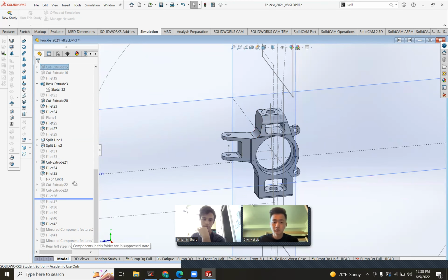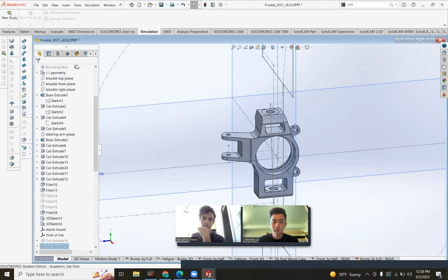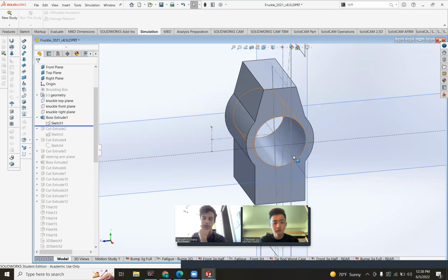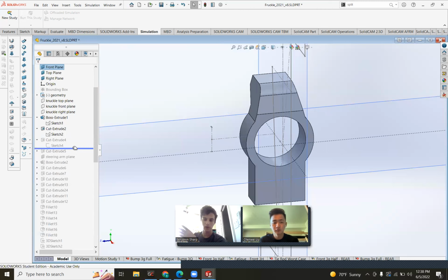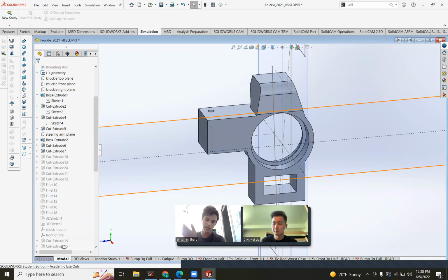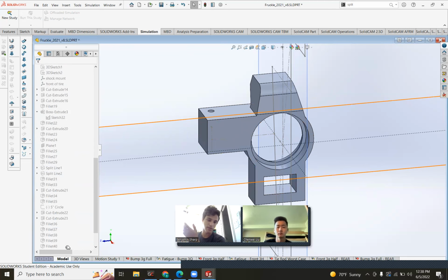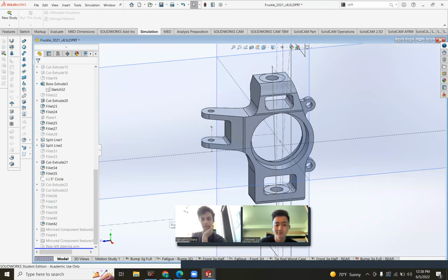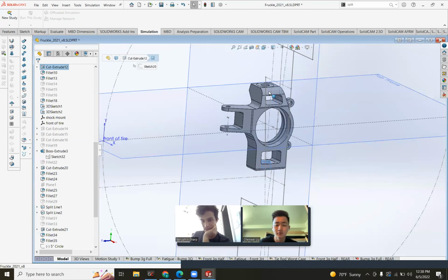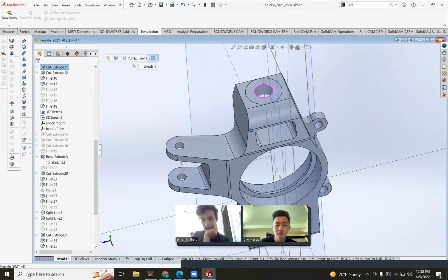So the important things are that you start with the geometry and then create this big block based on overall sizes, cut the profile, cut the bearing holes precisely, and then make the steering arm block and cutouts to fit. And the rest is, where do you want to have weight saving features? Where do you want to put your bolt through? It should be in the center of this face. And it is.